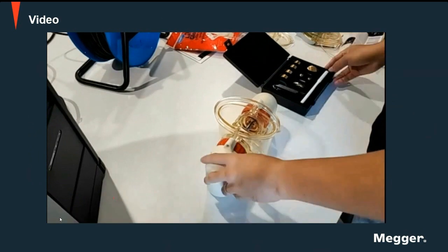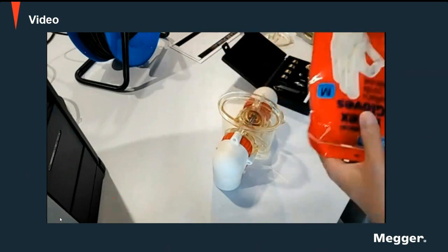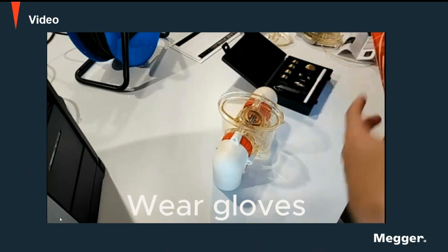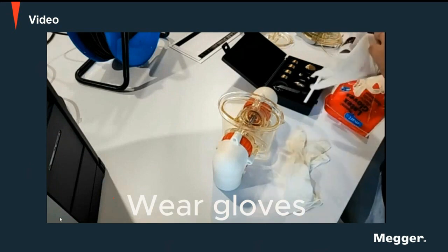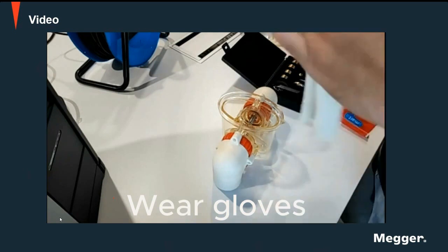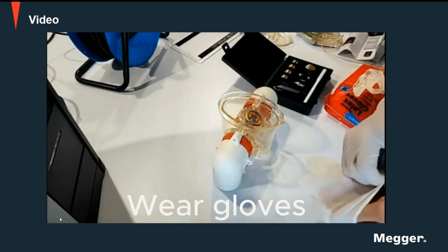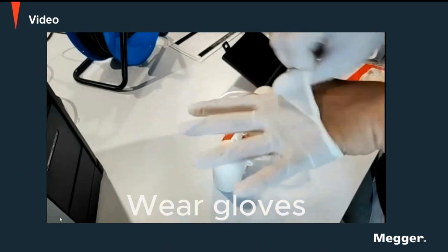First of all, when we do testing of the oil, we will use gloves. This type of glove should not be a normal rubber glove, because if it is a normal rubber glove, that means you get some powder or some particles on that glove. It should be medical gloves or food grade.